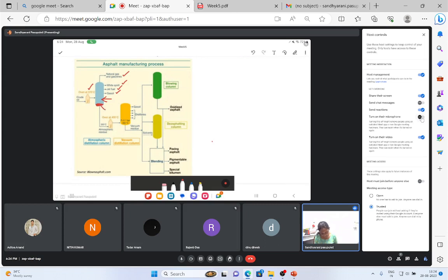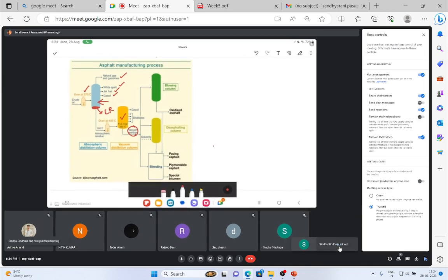We take this long residue, and again we subject it to around 350 degrees at 0.1 bar pressure. Then at the end there is some remaining material, which is called the short residue. This short residue has the probability of containing bitumen, the bitumen which we actually want.